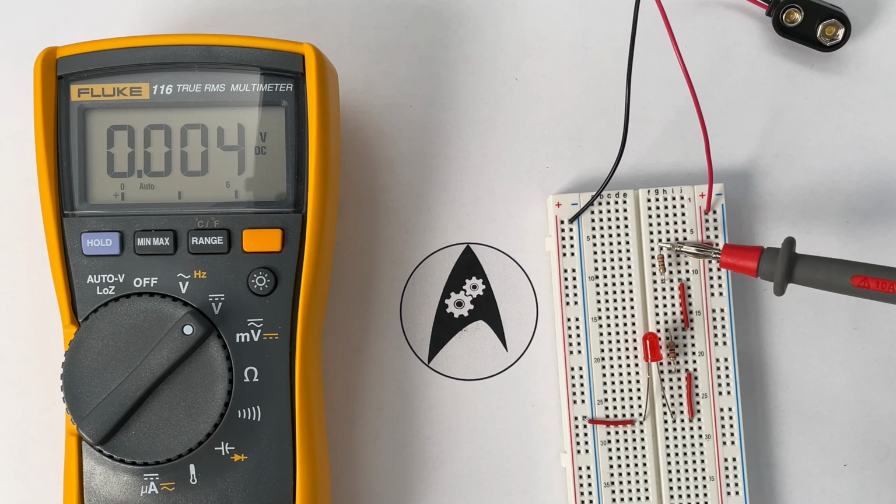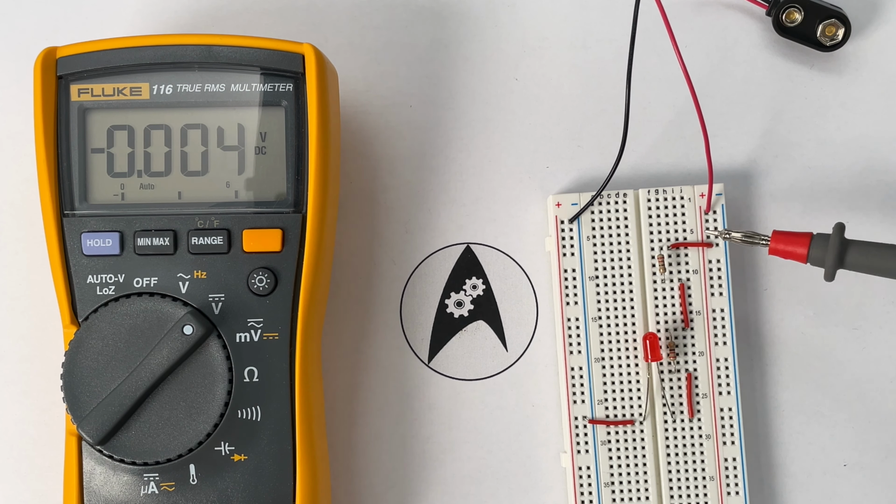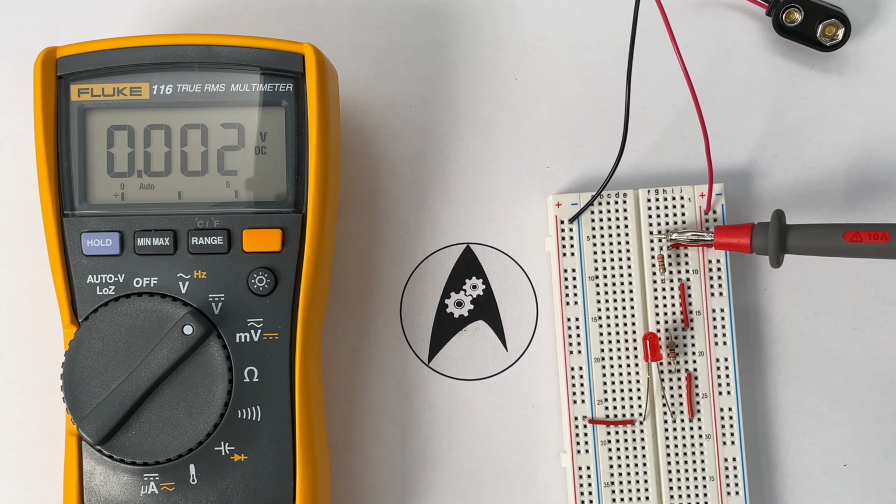Now, in the center part, the connection between the different holes of the breadboard is rotated by 90 degrees, which means all the holes in one row are connected to each other. So if I, for example, take row number 5, all the 5 holes in row number 5 are electrically connected to each other. However, the holes in the neighboring rows, 4 or 6, have no connection to row number 5. So power rails is top to bottom. The center part is always, the rows are connected left to right.